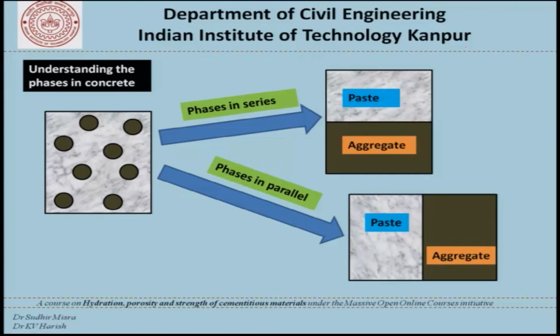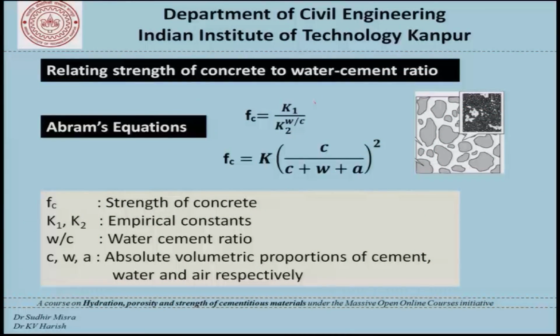Now, we have already seen this picture, which is in terms of trying to understand the application of load, whether the paste phase and the aggregate phase are to be taken in series, where we are talking about the stress being equal in both the cases, whereas in this case if we apply the load, it is the deformation which is the same in both the cases. We have had some discussion on these pictures and models.